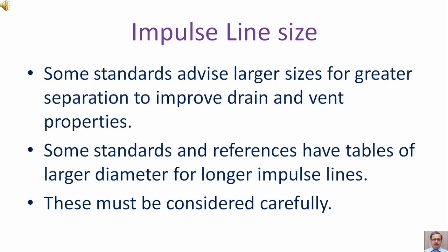Some standards advise larger sizes for greater separation to improve drain and vent properties. Some standards and references have tables of larger diameter for longer impulse lines. These must be considered carefully.